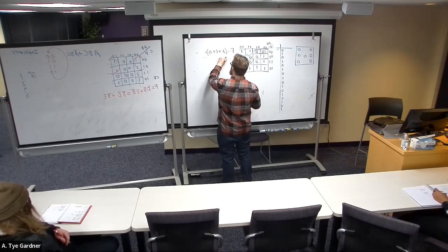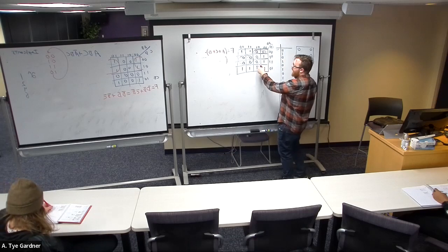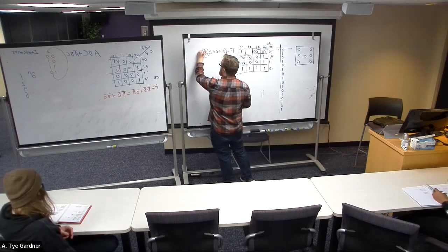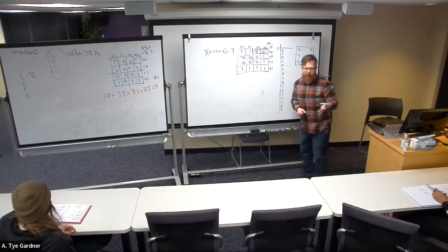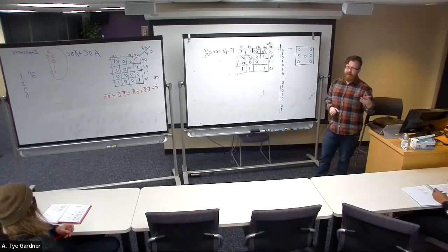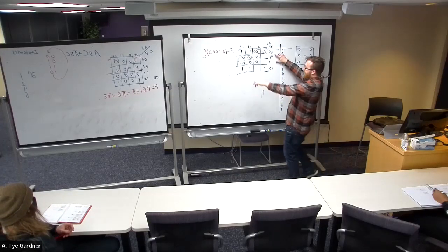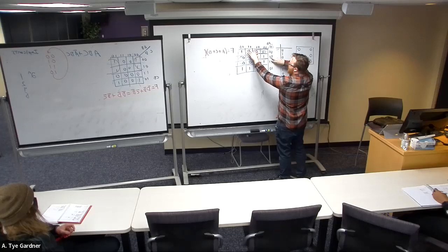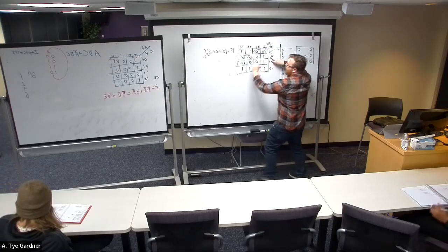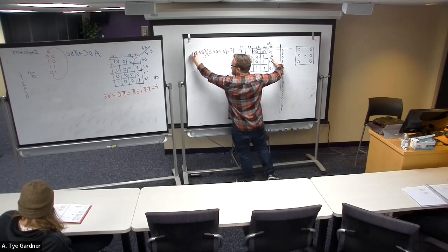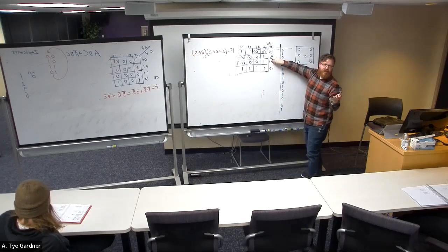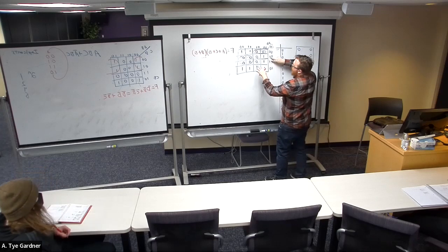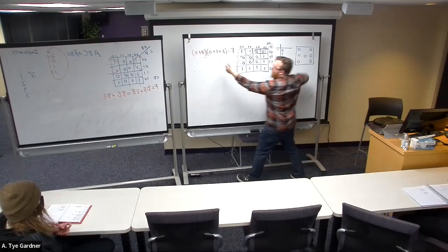Now it looks like I'm going to have to do a new row. This guy is going to be easier. It's just going to have 2 variables in it. In fact, because of that, I'm going to be able to fix this. So I really mean AND, because last time it was OR, now it's AND. I need A or C or D, and let's check out this guy. C changes, D doesn't. A changes, B doesn't. So that means I've got B or D. I just start with what the variables are, and then I check whether they have bars or not. Those are ones, so they both get a bar.